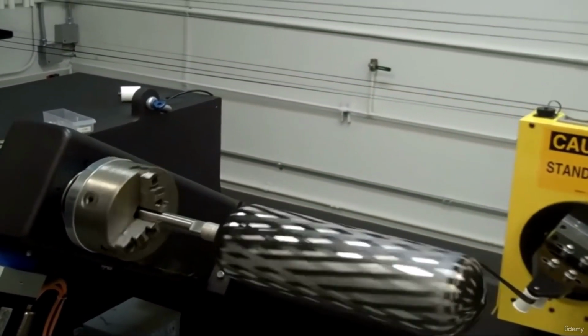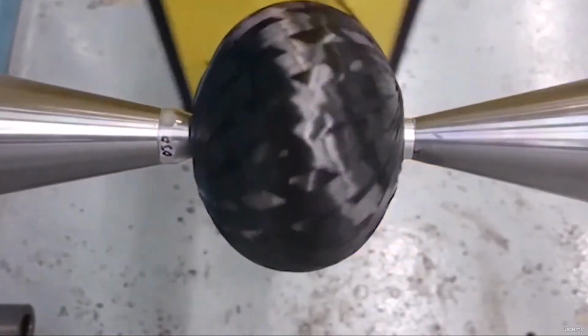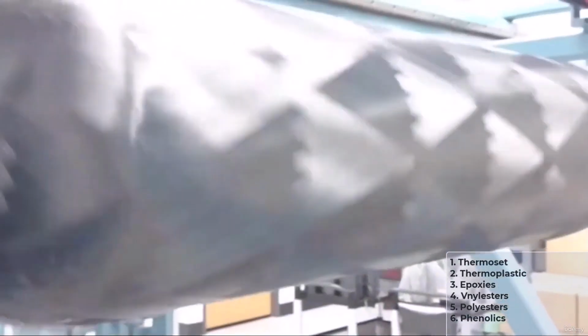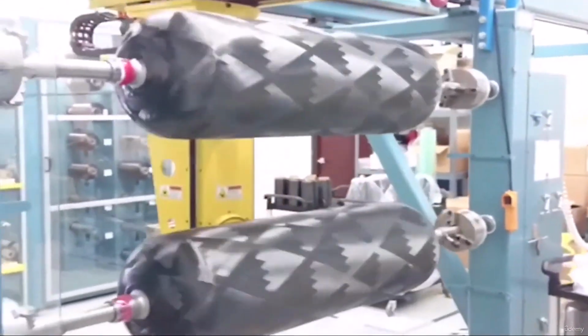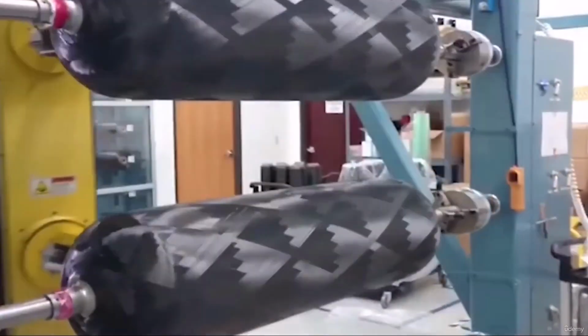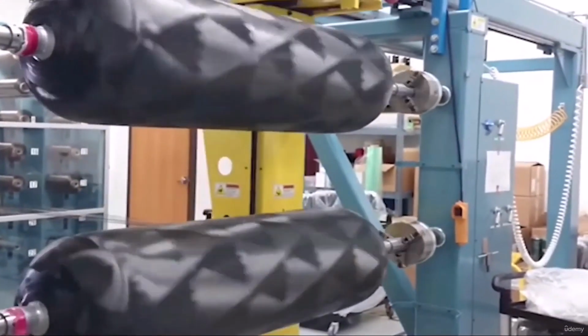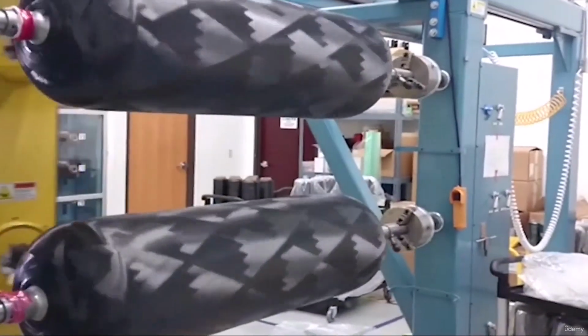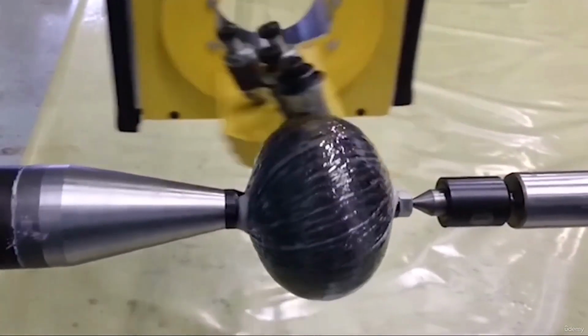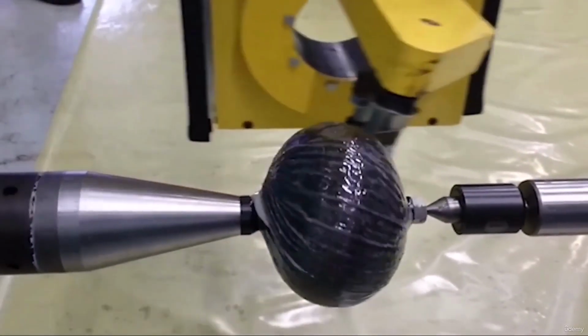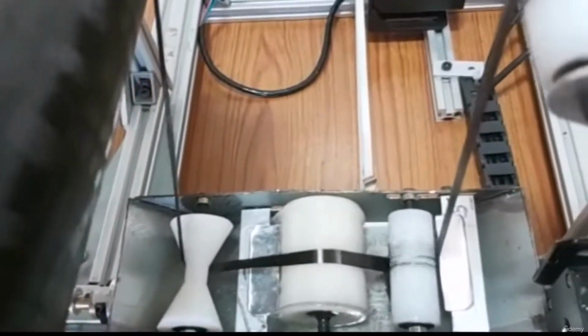As far as the material options are concerned, we can wind glass fiber or carbon fiber with different types of resin. We have thermoset resins: epoxy, polyesters, vinyl ester and phenolic resins. As far as fibers are concerned, the fibers are used straight from the creel and not woven or stitched into fabric form. However, tapes of any fabric, woven tapes, can also be used to wind. That is called tape winding. That is another topic. So there are basically two types of filament winding.